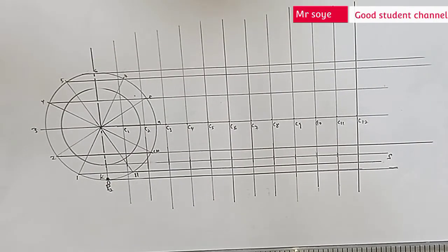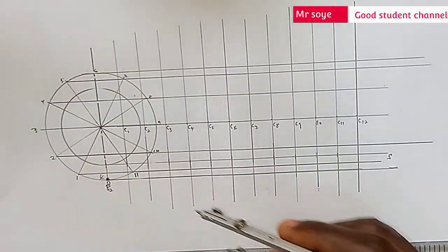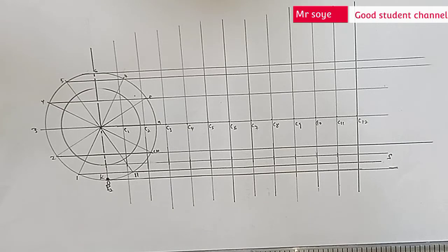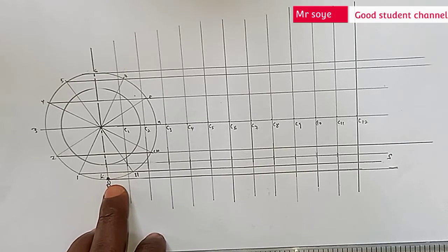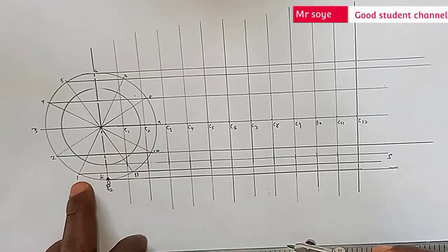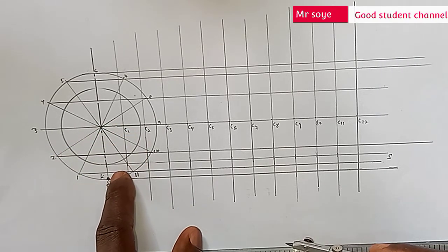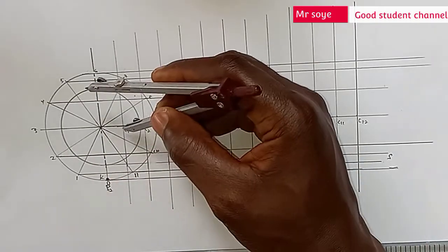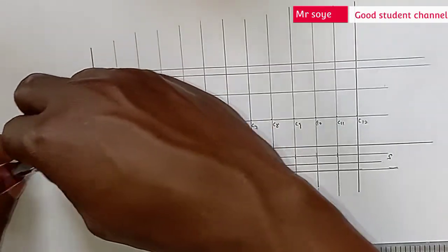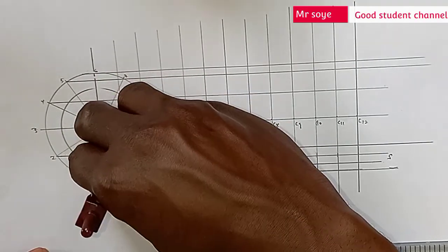After taking your compass to the radius of the generating cycle, the one that generates the point here, it has generated the point at 0. Now we'll take it to center 1 with the radius of the generating cycle. Mark line 1. So that's another point. Now let me confirm this again. Okay. Now put it at center 1. Mark line 1.